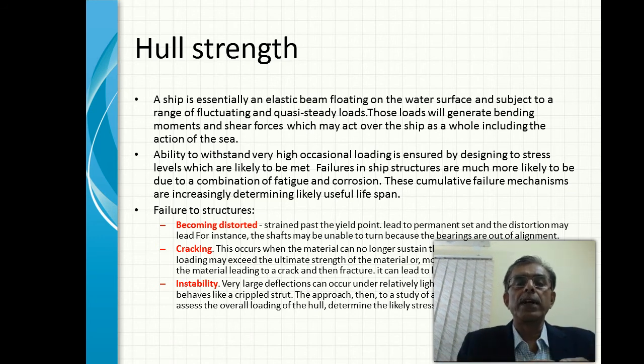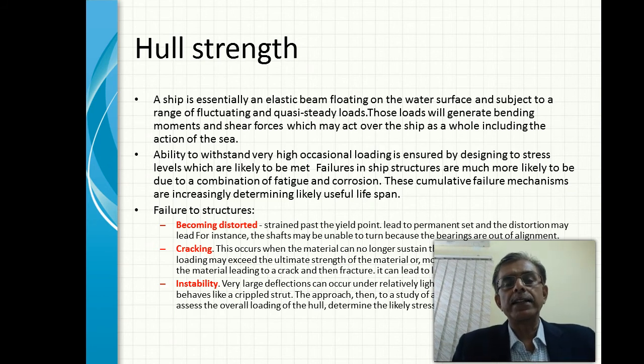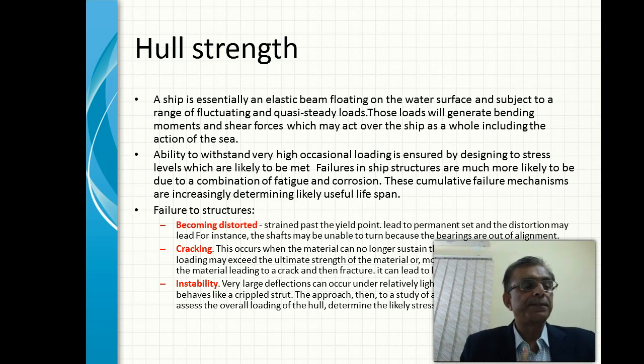At a very low stress, much lower than the ultimate tensile strength, the vessel can crack, and many disasters have happened due to cracks. These cracks can also emanate from certain scallops and holes, which are part of the construction to give air holes and water holes. So these are also sources where fatigue cracks can develop.